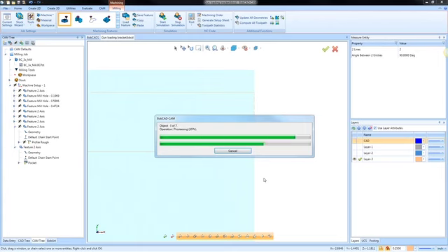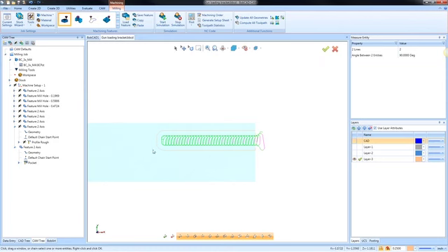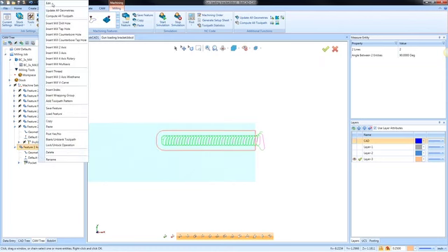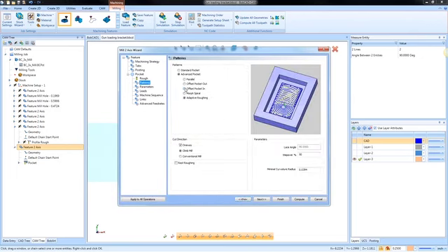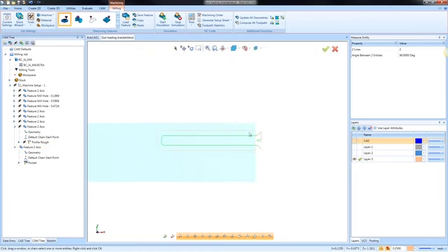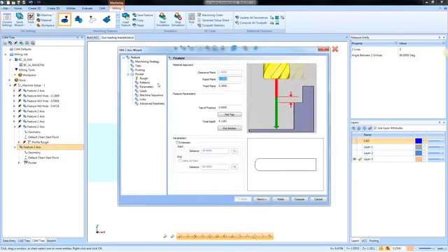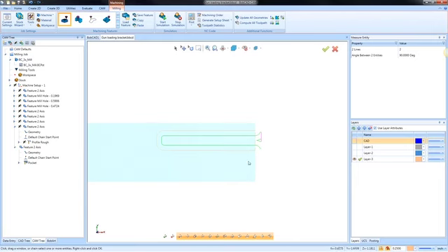And then what that will do is come in there with the trochoidal style cutting to do that pocket. If we don't want to do an adaptive routine, there's really not that much material here. We may do an offset in type routine, and we'll recompute that. And then that will work its way in, which essentially ended up doing a profile here. We could also edit this and do maybe an offset out type routine, and that will come in and work its way out.